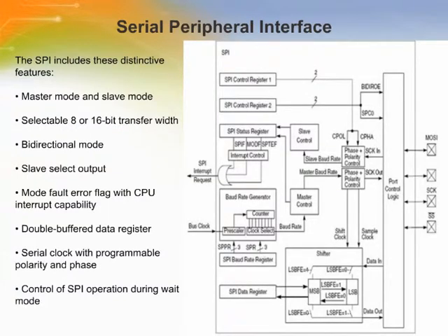The SPI module allows a duplex synchronous serial communications between the microcontroller and peripheral devices. Software can poll the SPI status flags, or the SPI operation can be interrupt-driven. It supports 16-bit data transfers as well as 8-bit transfers. This is controlled via a new transfer word in a control register.